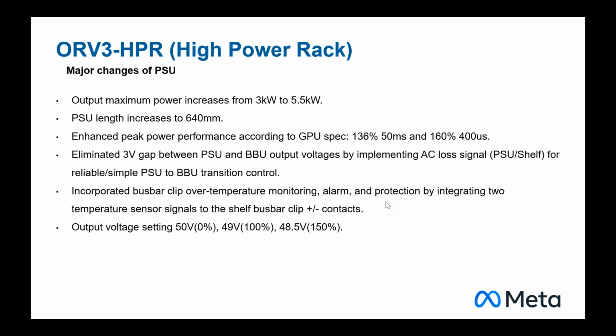I have a feature in the PSU and BBU design that makes this output voltage adjustable incrementally through a Modbus command. So down the road of the project development, we can fine tune the voltage setting. Let's say the DC-DC designer may say, hey, can we have 49.5 instead of 50? Yes, that can be done. So I'm also trying to get feedback from the downstream DC-DC designers. Which bus voltage do you prefer? 50, 49.5, 49, or what else?